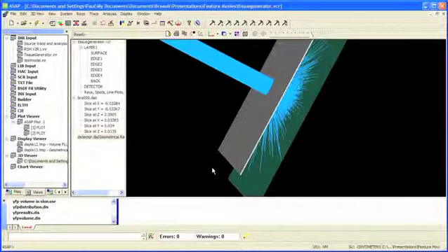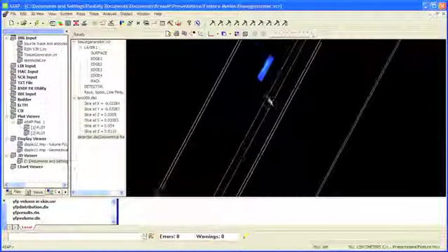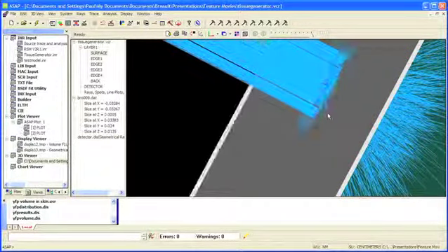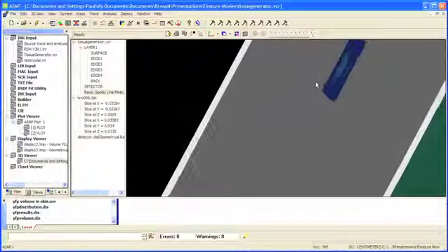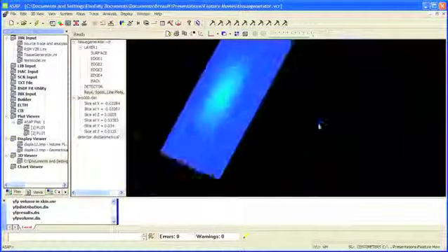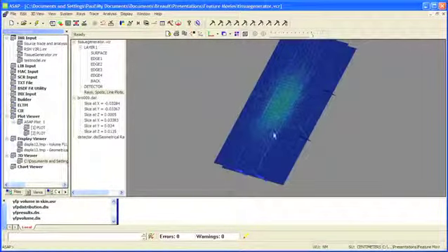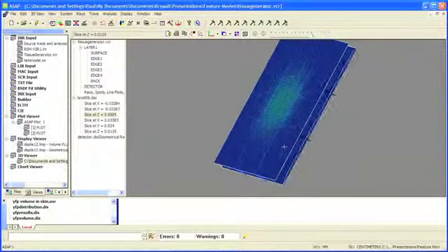With the tissue generator, ASAP possesses the capability to characterize any type of tissue based on user-defined parameters. These tissue models could be useful to model optical systems for extracting optical properties from tissue samples in laboratory settings. In this model, we have a 0.2 millimeter slab of tissue, which is illuminated with a 630 nanometer light source. We can examine the scatter as it passes through this particular slab of tissue, as well as the absorption within the tissue using a voxel system in all three dimensions.